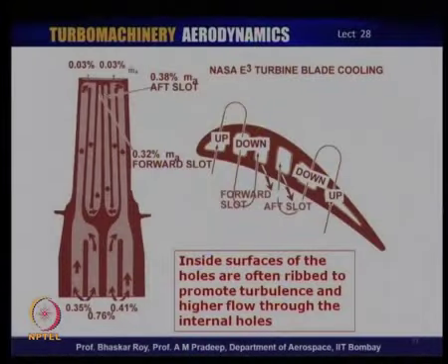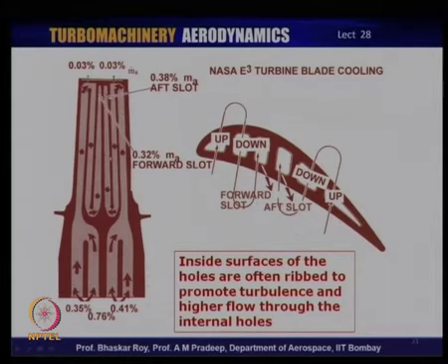We can have a look at a rotor blade, in which the cooling technology is even more elaborate, because the blades are rotating. Remember, the flow inside will be feeling the centrifugal action. So, by centrifugal action, the flow will get thrown outwards from here, as it comes in from here, and that will give enough impetus to the flow to go through this channel and then finally come out through the tip.